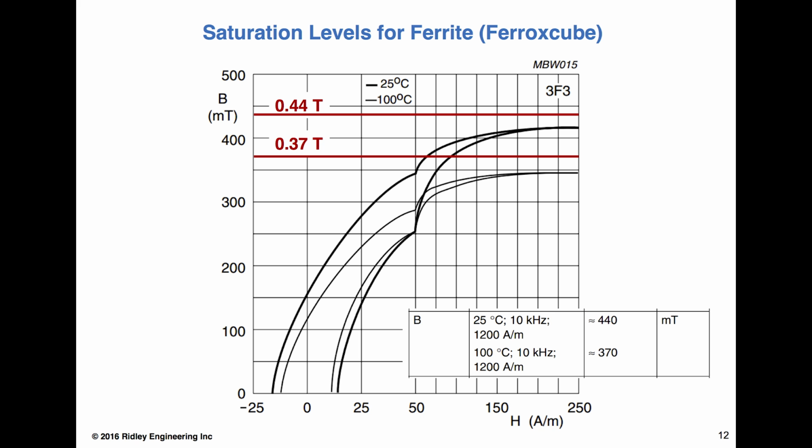I know there's going to be talk about this at the PSMA meetings in APEC, where they're going to have some measurement setups and so on. But one thing that always concerns me on measurement setups is that when we used to do research on ferrites at Virginia Tech, the only way to get at the true core loss was calorimetry, because the parts are so good. And extracting the real loss measurement from electrical waveforms is a real challenge.